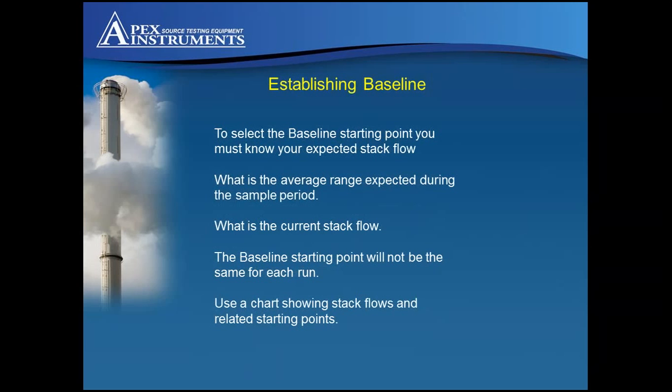Okay, all right, establishing the baseline is probably the trickier part of having a successful run. To select the baseline starting point, you must know what your expected stack flow will be, and you also need to know the average range expected during the sample period and what the current stack flow is. If the current stack flow is at a high end, you would select a higher starting point, allowing the rate to adjust downwards. The baseline starting point will not be the same for each run.